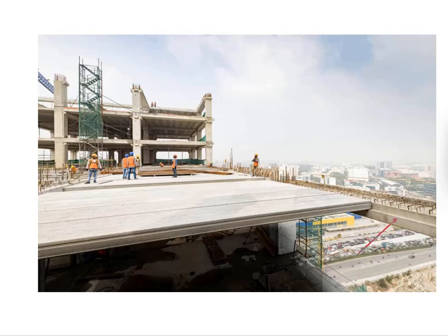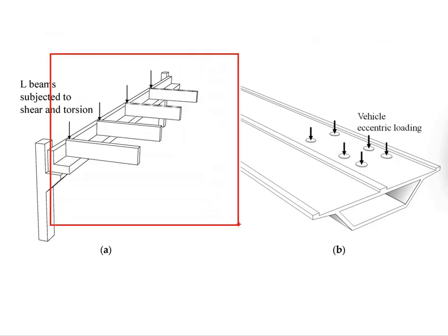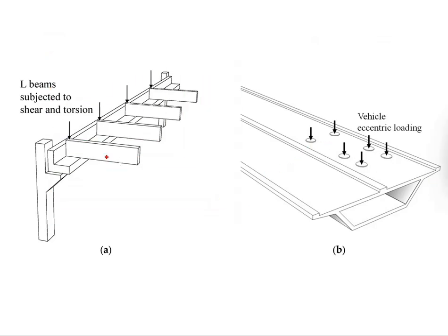What if we are using this beam? Then you will need to design this beam here so that it has sufficient torsional resistance to temporarily resist the torsional force when you are first installing one side of the member. Later, when you have the hollow core slab on the other side, then the torsional force is balanced. These are some other examples when torsion can happen, especially on the HB, where it is used to support the loads from the incoming members.